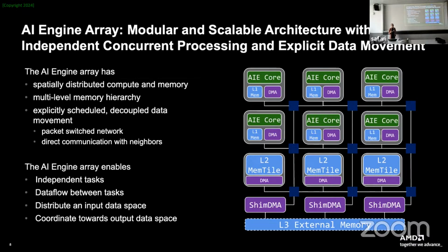And since this architecture is so adaptable, so configurable, you can implement different types of parallelism on it. Either you give multiple compute tiles a different task and you build a kind of dataflow, task-level parallel pipeline. Or you can give them all the same task, but then, for instance, use the broadcasting feature of the interconnect network to duplicate data, if that would make sense, so that you get to a more data-level parallel implementation, if that makes sense for your workload, and you can mix and match.